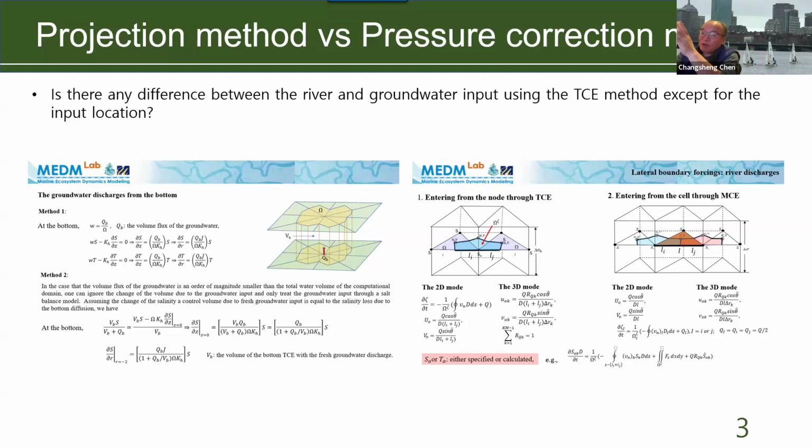But which method is good? When the resolution becomes high, the two methods converge to the same result. However, if the river flux is very small, you had better use the momentum flux method. Don't use the sea level method, because the sea level method puts the water in at one point. Very low salinity can come out at one point.